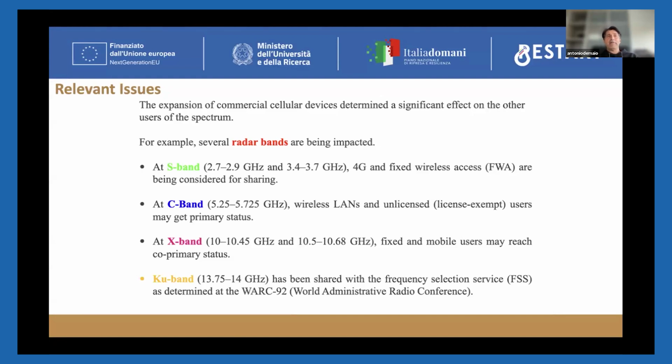Another area of current concern to radar users is the allocation of spectrum to communication systems such as the WiMAX, the LTE, the 5G, in the S-band portion, which is also adjacent to the allocations for air traffic control in maritime radars. And also, there's the United States National Weather Service Next Generation weather radars. They operate in frequency interval around mid of the S-band.